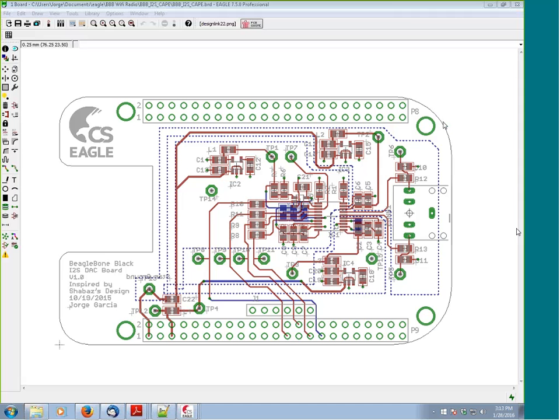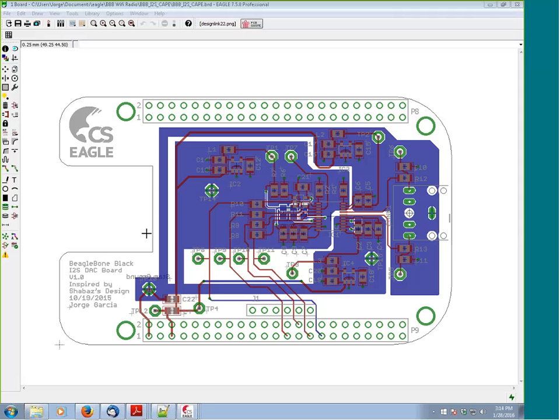So what we end up doing is, for those parts around here, this is the digital section. Signals are coming in over here. For any circuit to work, you always have to have a return path. You have to have the ground come back. Basically, I keep all of those fast transients limited to this polygon. That's the idea of doing the separation. Any fast transients are limited to here, and they only return over here.